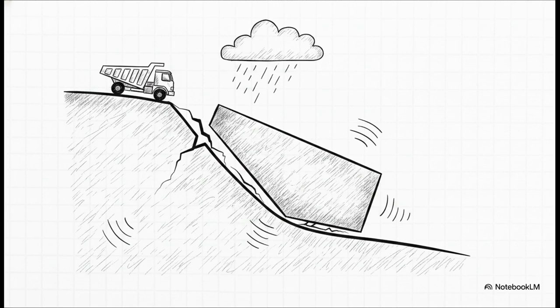Scaling up from microscopic pills to massive mountainsides, engineering the angle of repose becomes a literal matter of life and death. When engineers are dealing with infinite slopes, like the long face of a mountain, or finite slopes of known dimensions, they have to calculate a factor of safety based on the soil's natural angle. If that naturally stable angle is exceeded, perhaps due to sudden water erosion, earthquakes, or excess loads from heavy vehicles, you risk terrifying earth slip failures.